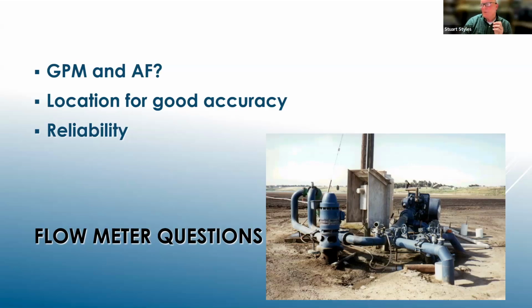We've been working with magnetic meters now for a number of years, and I used to have slides on it because it was the new thing, and it's really not the new thing anymore. It's kind of the standard that a lot of folks have gone to. The main reason that growers are going to mag meters, the magnetic meters, is that they don't have a large requirement for the number of straight sections upstream. So we could actually put a mag meter in this pumping configuration here, and it would work in that application. We have quite a bit of information on mag meters online if you're more interested in that topic.